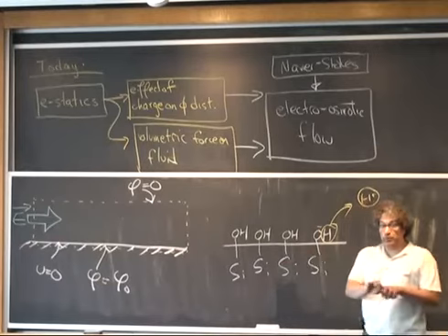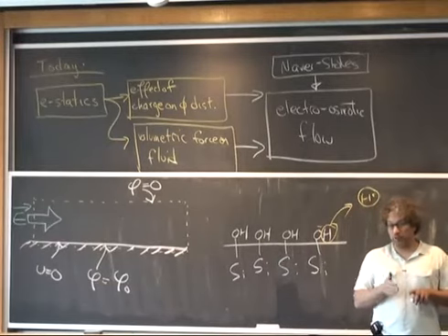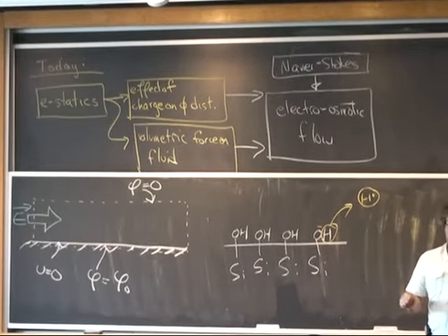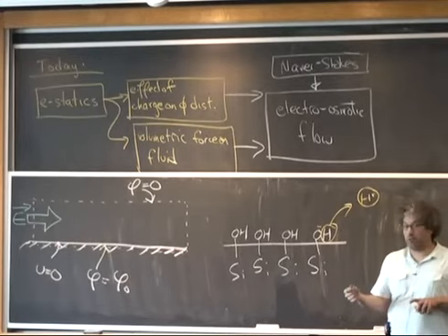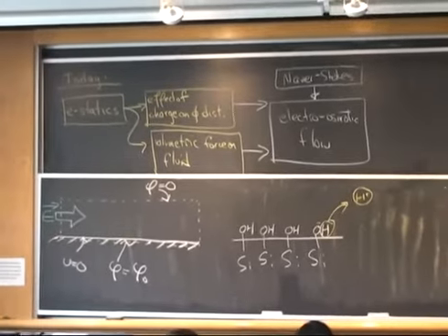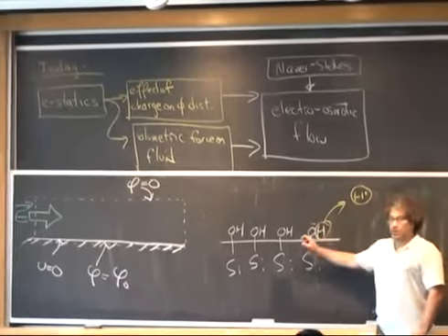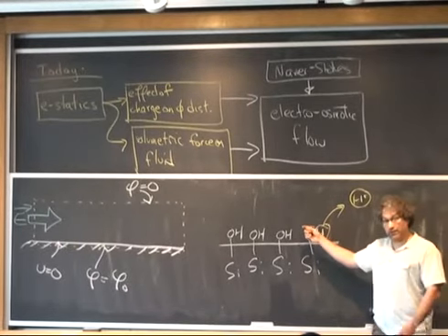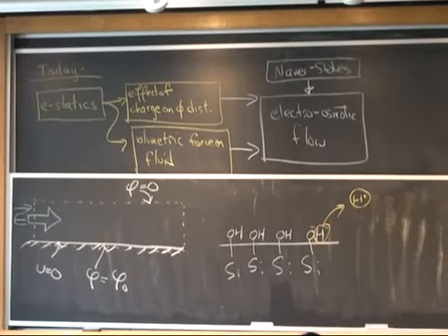So if I take a tube and I make it out of plastic, I apply an electric field, I'll get flow and it'll have a specific velocity. If I make the same tube out of glass, that flow will have a different velocity. If I make the tube out of alumina instead of glass, the flow will go in the other direction. Everything is tied immediately to that chemistry. And furthermore, it means that if I have salty water at pH 7, I'll get one flow rate, and if I have salty water at pH 5, I'll get a different flow rate. So viscosity still affects this system as we would expect in all fluid mechanics, but now also all the chemical questions do. Other questions?